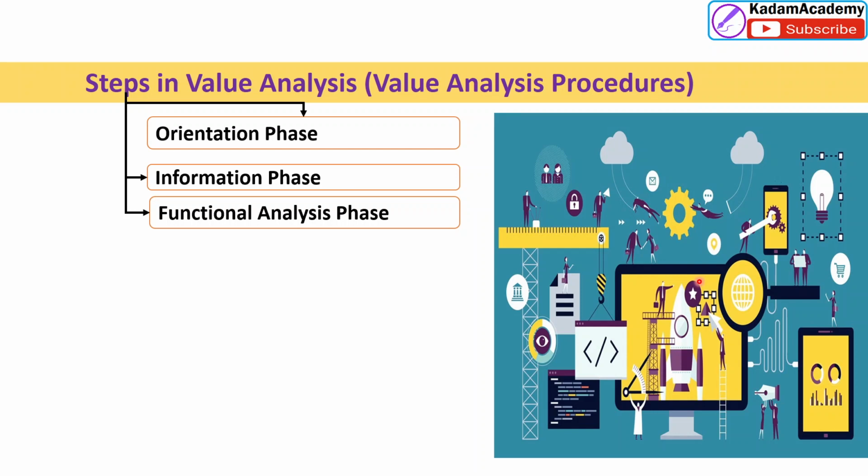It can be represented as: list the components of hardware, and prepare the verb-noun description of the functions of each assembly and component. If the product has assemblies, then for each assembly and component we prepare their verb and noun, and establish the cost of essential functions. That is important here.